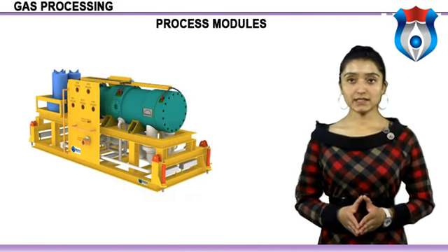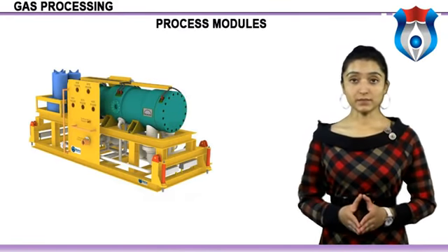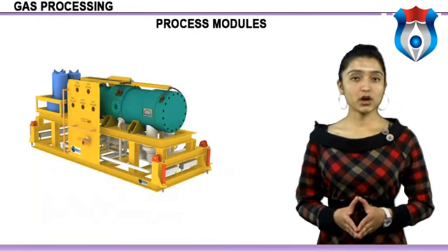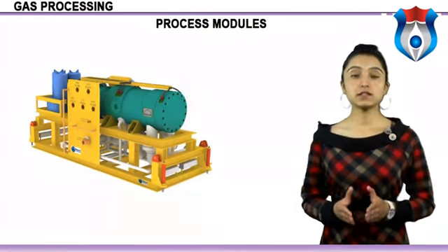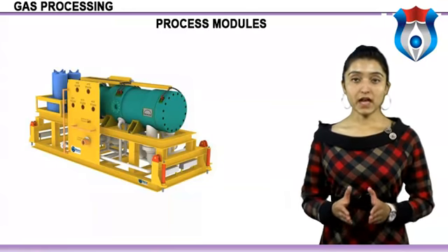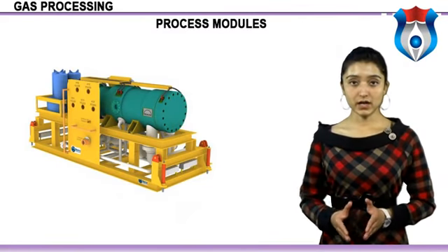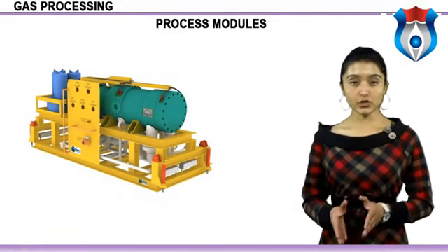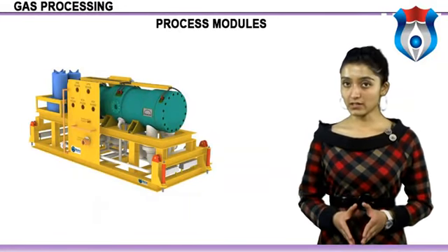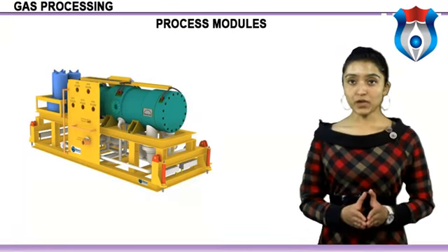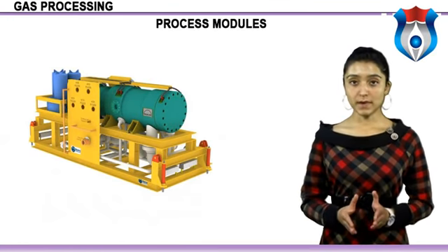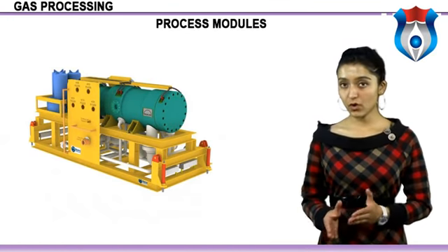Natural gas processing also includes acid gas treating. In addition to heavy hydrocarbons and water vapor, natural gas often contains other contaminants that may have to be removed. Carbon dioxide (CO2), hydrogen sulfide (H2S), and other sulfur-containing species such as mercaptans are compounds that require complete or partial removal.